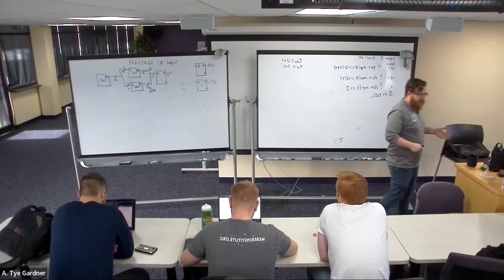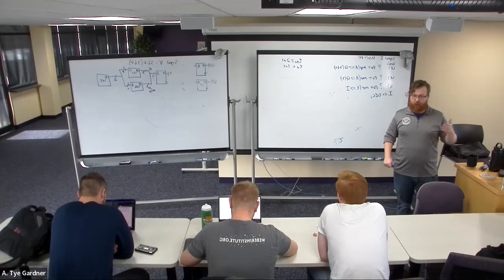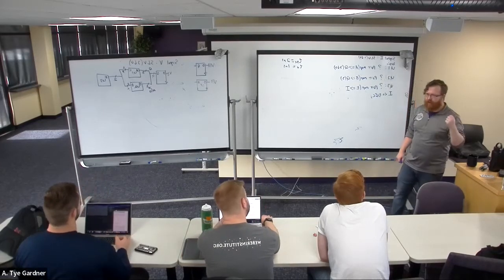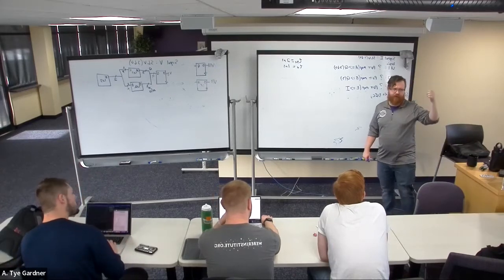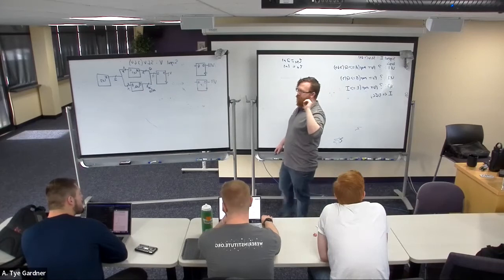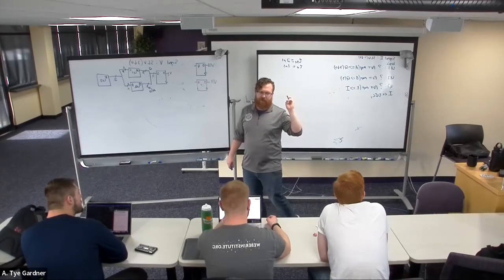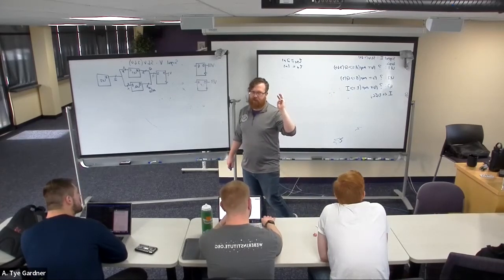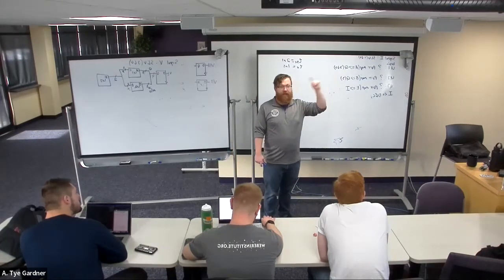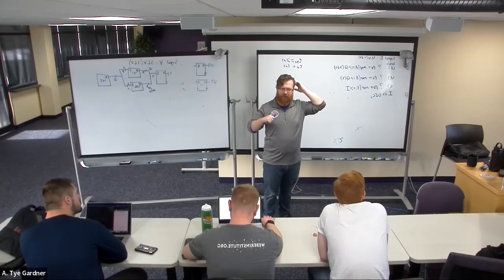So when you're working on your project 1, your top level file is going to be called ALU. The ALU is going to need 5 different component declarations, right? Because, well, you can technically do with less, but you're going to have your adder, add with carry, XOR, load and hold. So you're going to have 5 component declarations, sorry, 6, because you're going to have a mux. You're going to have a 5 input mux with the 3-bit select signal.